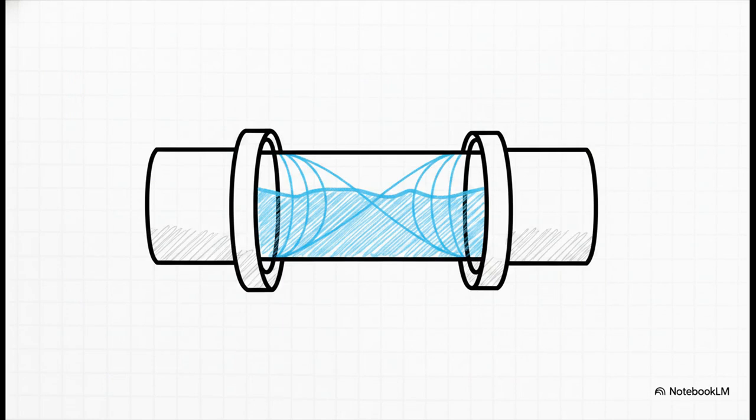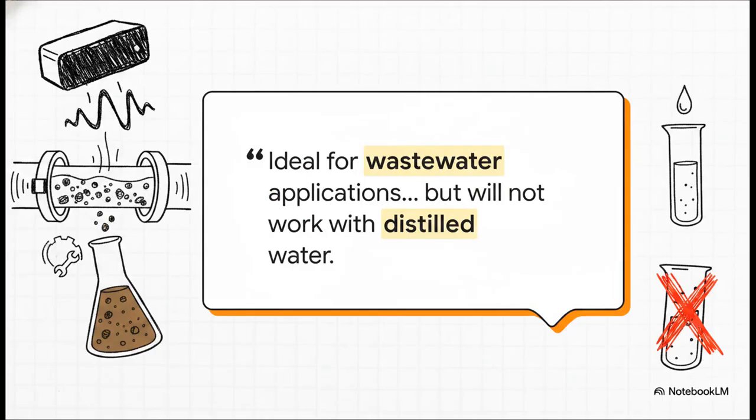Now, among the different types of flow sensors out there, ultrasonic flow meters really stand out. They are non-intrusive volumetric flow meters that use acoustic vibrations, specifically Doppler and transit time technologies, to measure the flow rate. What makes them so highly prized is that because they don't block the pipe at all, they cause a very low pressure drop, require incredibly low maintenance, and offer fantastic chemical compatibility since the sensor itself never degrades in the fluid. But here is the fascinating gotcha detail with this tech.